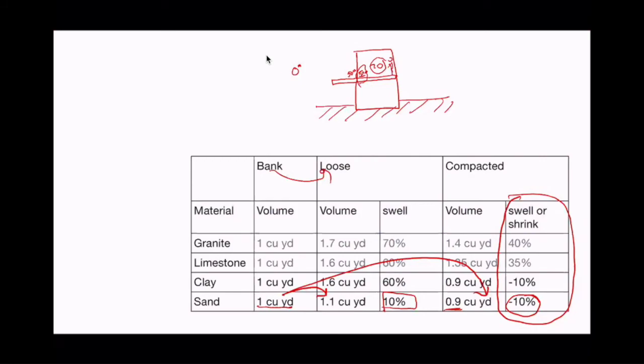It has a large angle, and that cold floor is going to be robbing your skin of radiant heat, which is a crazy concept. So it's going to be cooling the air, cooling your feet, and cooling your skin that sees the floor that it cooled through conduction. So anyhow, it's bad. You don't want that to happen.